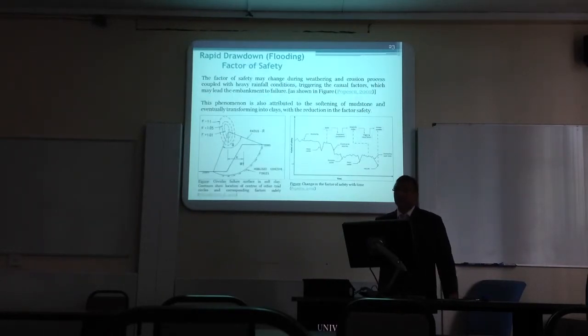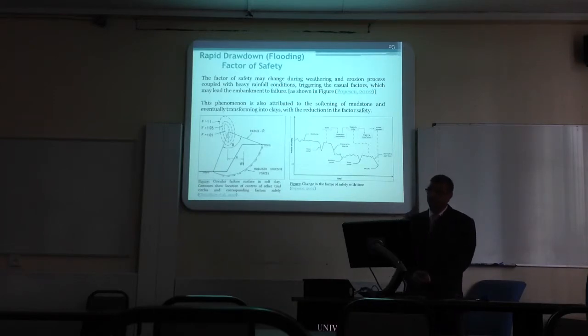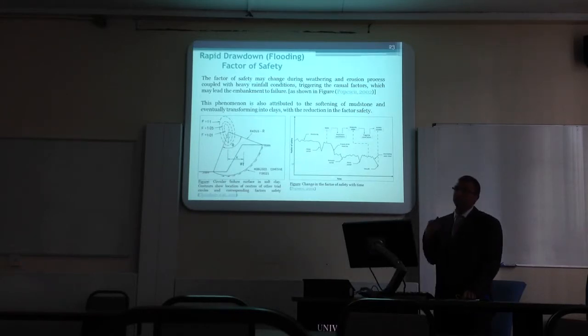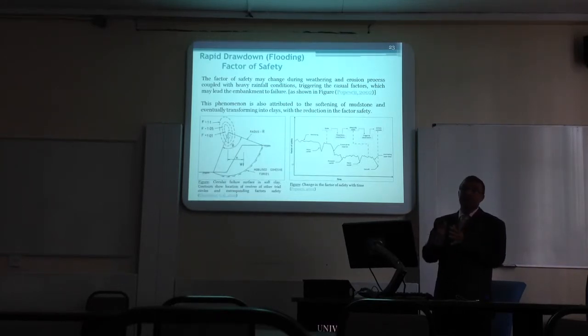The factor of safety may change during the weathering and erosion process. As I said earlier, it is hard to establish factor of safety based on the height only. It may lead to failure because of the triggering factors and rainfall condition. As seen in mudstone, if mudstone is getting wet due to rainfall or water, it is converting towards clay. So of course the strength is decreasing, and the factor of safety will be affected accordingly.